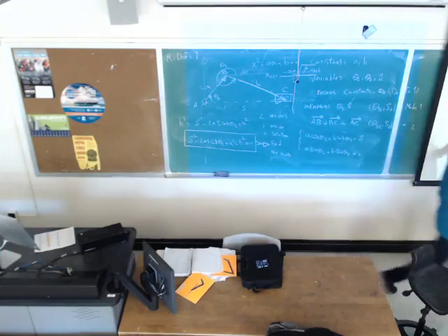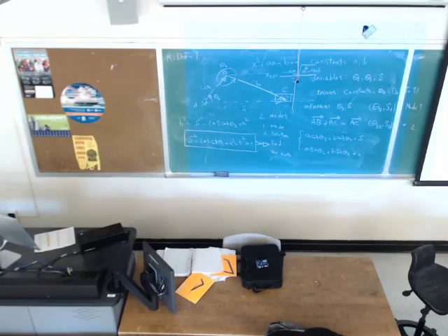This slide is covering what I explained here. We will get 2 answers for theta 3 from the cosine equation, theta 3 and negative theta 3. We will get 2 answers for theta 3 from the sine equation, theta 3 and 180 minus theta 3.